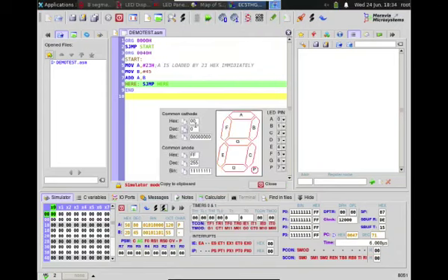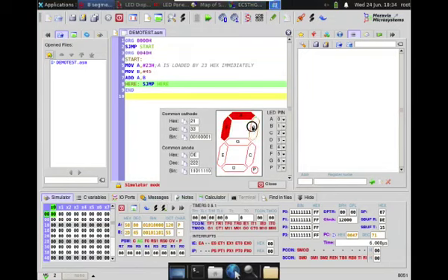Here we can generate common cathode and common anode type codes. Say if I draw 0, and here I put A as a port pin 0, port pin 1, 2, 3, 4, 5, 6, 7, where P means DP. Here we get the common anode configuration code in hexadecimal, and this is binary, then the common anode and common cathode codes.